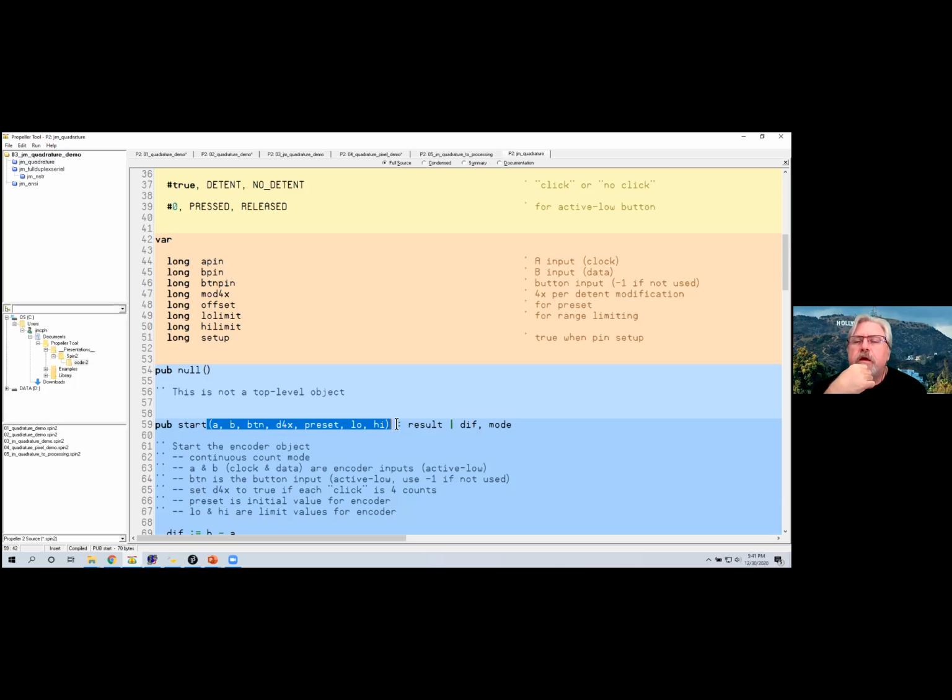without completely resetting it. But let me give you a real world example. If you get in the car and you turn on the radio, the volume level is going to be wherever you left it last time, even though it's not a physical potentiometer anymore. It's a rotary encoder. The way that works is when you make a volume change, the software in the radio is saving that volume level to an EEPROM or a flash or some non-volatile memory, and then the next time you power up, it's stuffing that value into the encoder. I have done that in the past with P1 encoder cogs, where I could actually tell the encoder, hey, here's your new value, deal with this. We can't do that with the smart pins. Now, that doesn't mean we can't have that functionality. We just have to work around it.